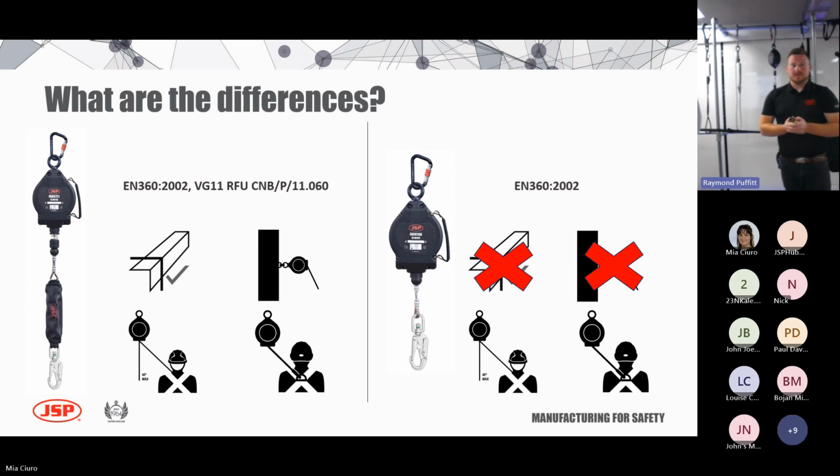Okay. So the fall arrest blocks. This is probably the slightly more confusing one on the market, because you always see these blocks being used. A lot of the time you will see them being used connected to things like leading edge, formwork, or handrail systems, etc. And we need to think about, are these then being used horizontally? Where are they being connected? Do people sometimes not look above them? They don't have anything above them to connect with, so then they're using a standard block that's been tested purely for vertical use, as horizontal.